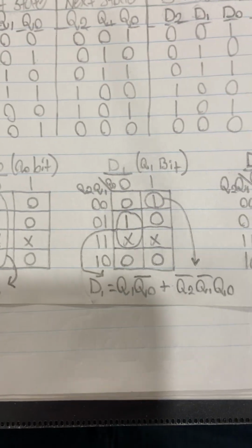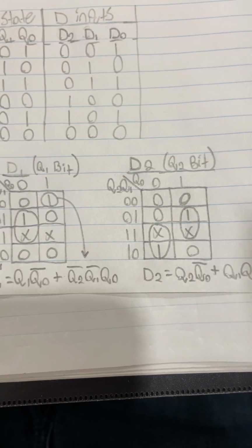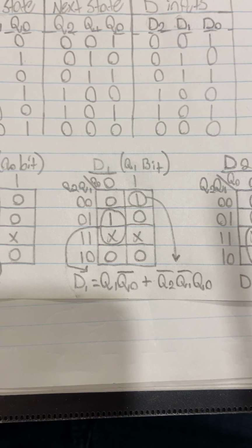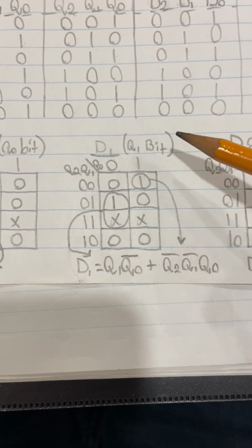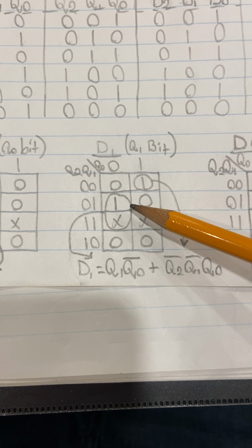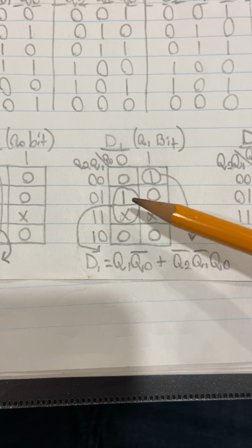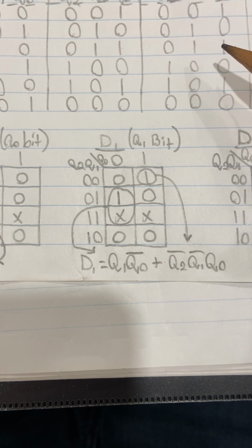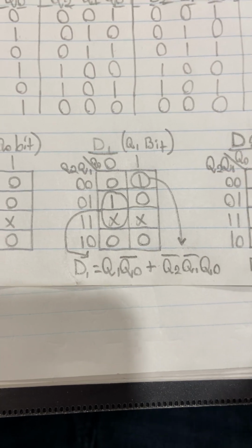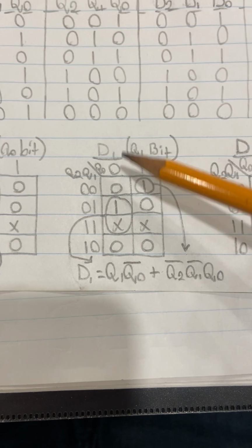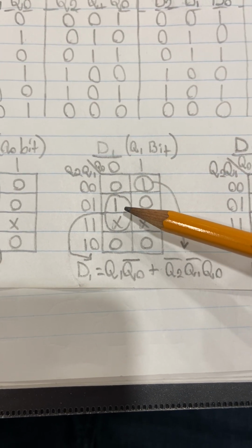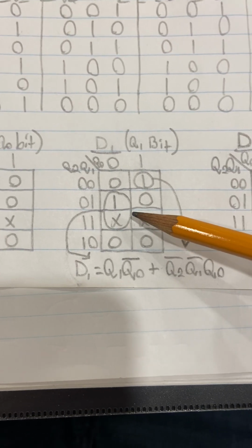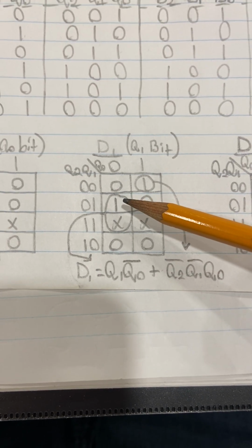And then we continue on and do that for the other two bits. So I'll show you them here and you can look at what I've done. So basically we did the same thing as before. We come up with a grouping here because you can't group zeros together. You can't group lows. You can group ones and don't cares. There's wrapping rules and these types of things. You should review that if you need to. And we can say every time basically you group something together, you end up getting rid of one Q. So here we've grouped something, so we're going to get rid of a Q.